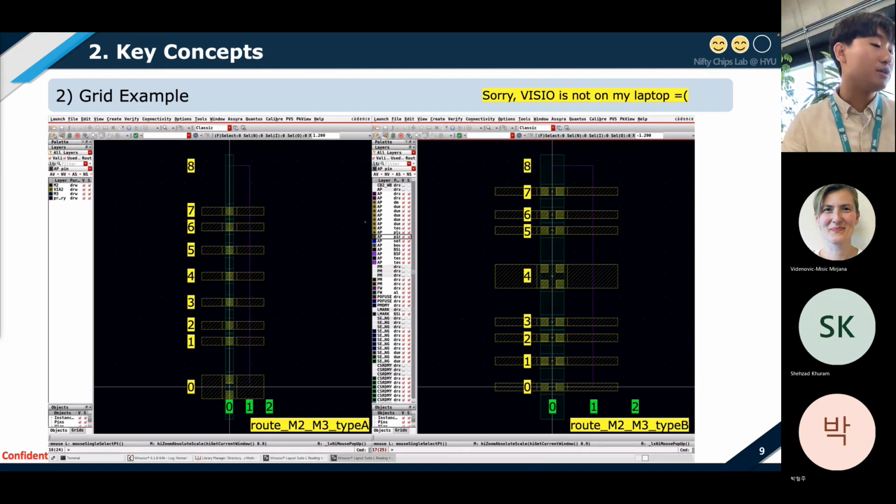And then the actual spacing on metal tracks doesn't have to be uniform, even if we use integer coordinates. There are many things to consider for layouts: local interconnects, coupling capacitance, and things like that. Grids repeat a specified number of tracks by circular mapping, and the interacting range is usually defined as the sum of the heights of NMOS and PMOS.